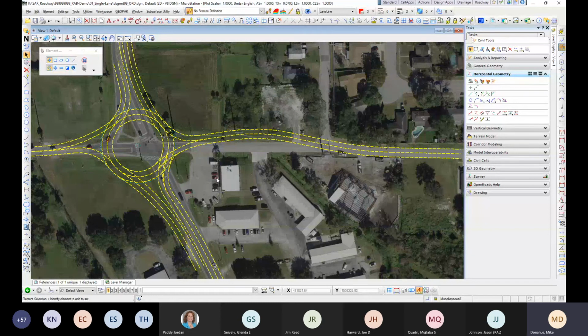It's actually getting let in about 3 or 4 weeks, I think. But to do that grading, I ran the template as far as I could. And once I got into my island areas, it just didn't seem to make that much sense to run a full template on the left and right. You can divide it and create a template for one side of the road versus the other. And I would do it with left and right.